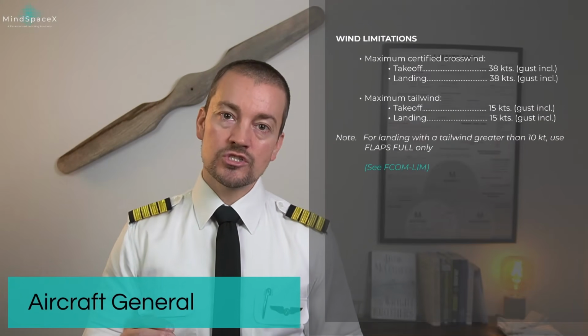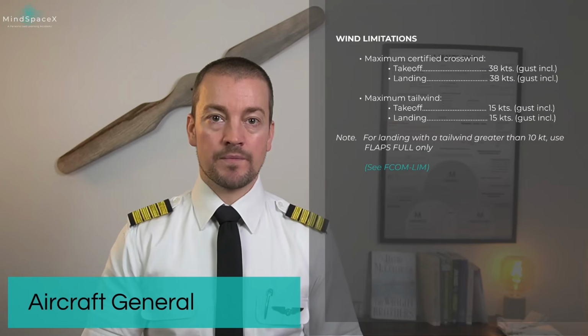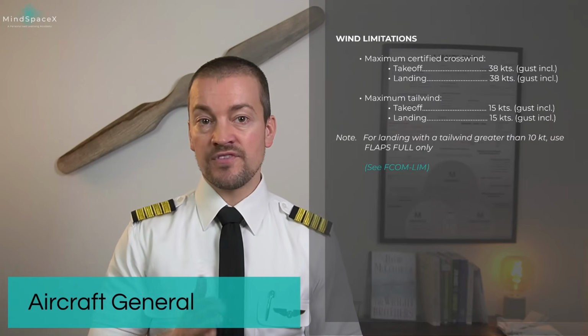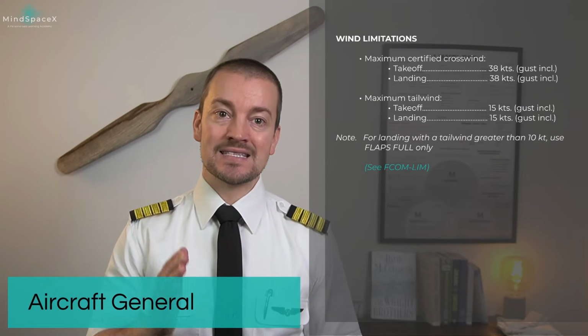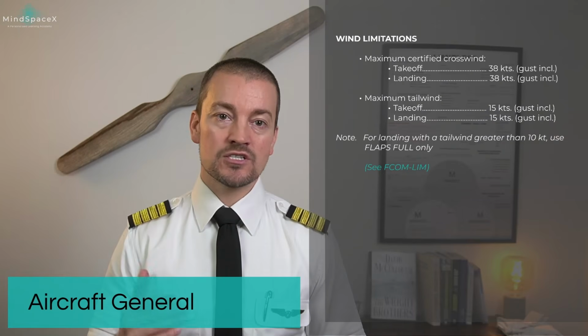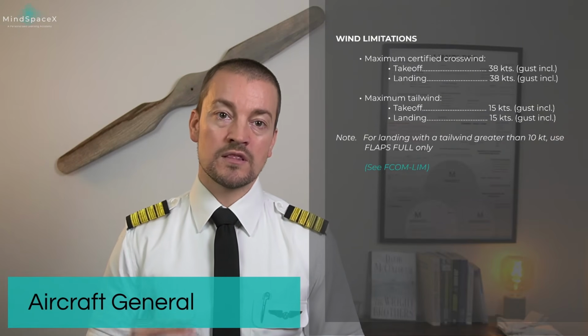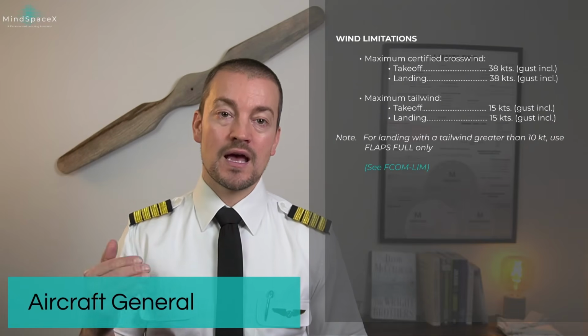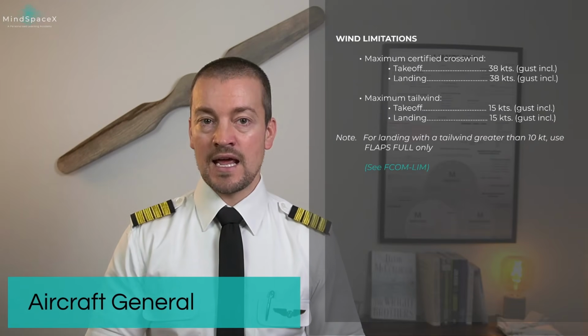Wind limitations also include, as I mentioned, tailwind. Maximum tailwind for takeoff and landing is 15 knots, and this is a limitation. The maximum tailwind limitation is placed on the aircraft to ensure that the airfoils, the wings, generate the appropriate amount of lift for takeoff and landing.